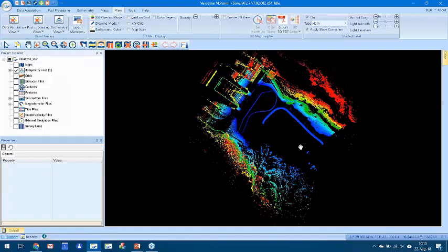The scanner is a spinning circular scanner that's mounted vertically, so it spins like a Ferris wheel, 360 degrees all the way around. And it collects data on all those axes. So when it's pointed straight down, it's seeing the mount, and it can sometimes see part of the boat where it was mounted if you don't have it up on a great big tower. It also has a limited range. It's a small system, so it only is valid out to about 100 meters.